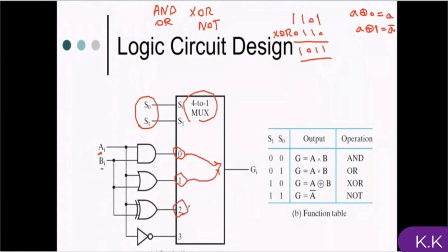So in order to make it possible for your ALU to perform it, we need a module similar to this one. Here we talk about 2 bits only, A index, B index. We use a 4x1 multiplexer as a selector. When it is 0, 0, input 0 will be in the output.